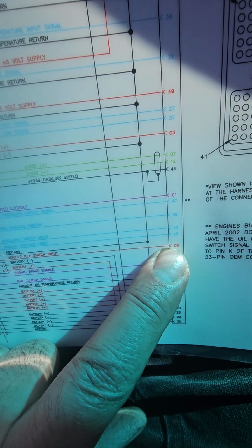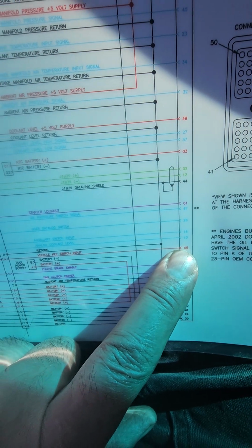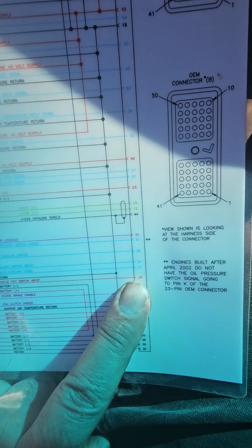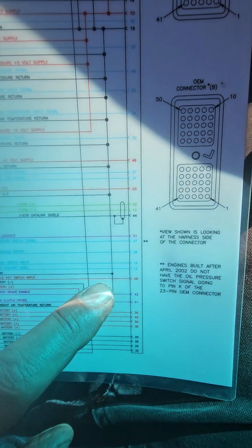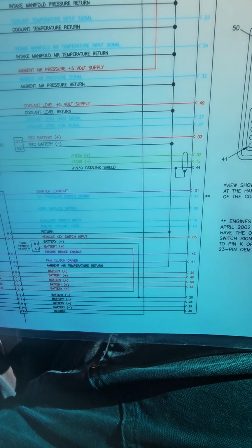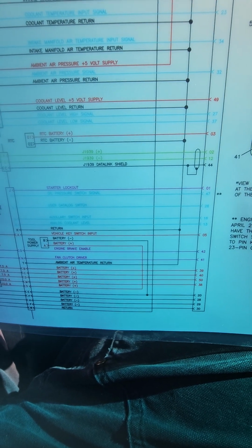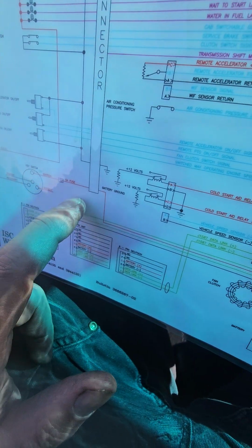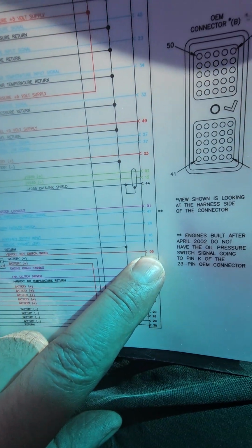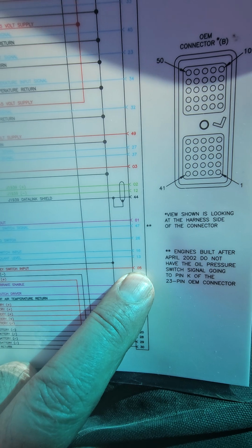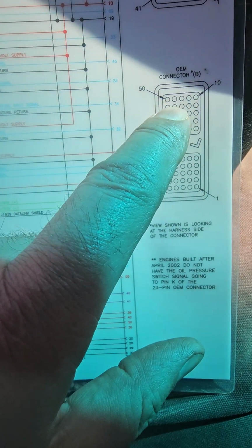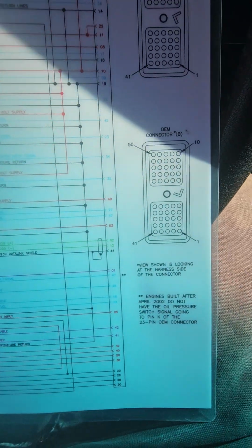The load should come from the actual electric component that it's powering, and that's where the voltage drop should occur. The wiring should not be the electrical component. That's the definition of a voltage drop, when you have an unwanted draw in the actual wiring. This should be an unclogged artery, a healthy artery. So that was reflective in 3/4 of a volt less at position 5 through the ignition key than position 50. So that's what makes this whole thing interesting.